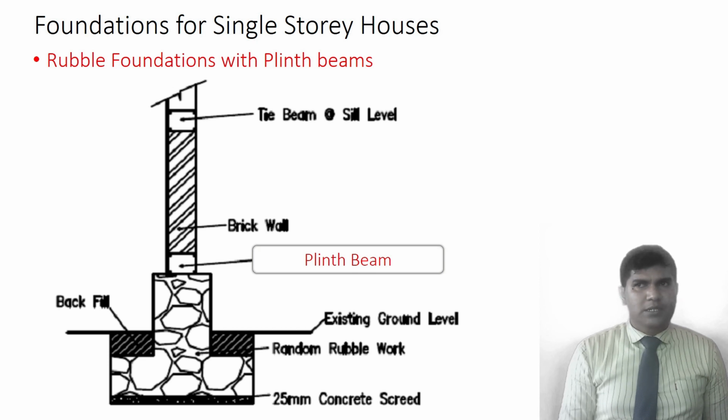So actually the plinth beams are introduced when the soil condition is going to be weak. Then we use the plinth to distribute the load on the soil.